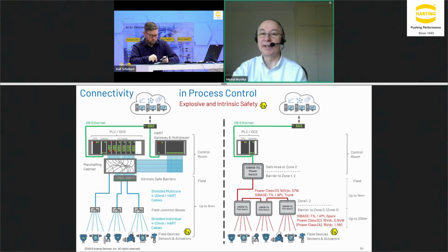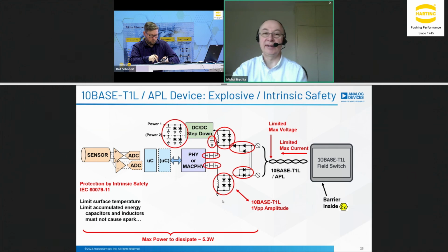If this device needs 20 watts, 50 watts, can the system deliver 50 watts? That does not work in this environment because it needs to be intrinsically safe. So the power classes are fixed and there is a very tight regulation on how the cables are connected and so on. So that's a different level of power over Ethernet, but it is still single pair power over Ethernet and belongs to that category. And the challenge there in the device design is the protection.